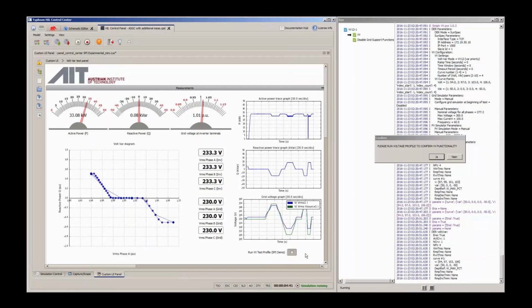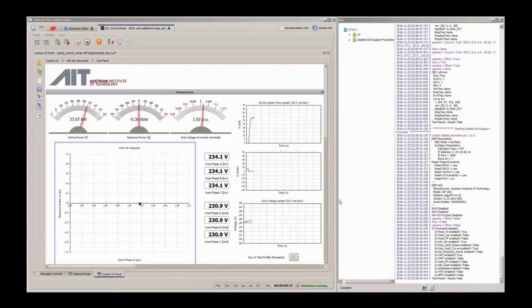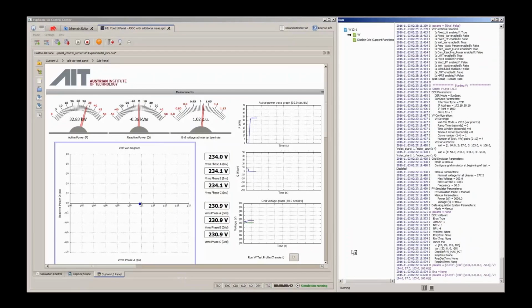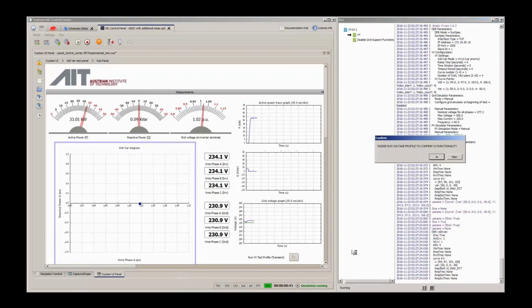Okay, so I think we can stop this video right now, and I would like to show you an example of a test procedure which we use to determine the transient response. The first test was mainly related to determining the accuracy and the slow response of the controller. Now in this example, we do a very fast voltage change to see the transient response of the converter.